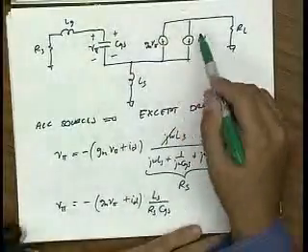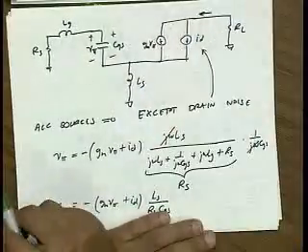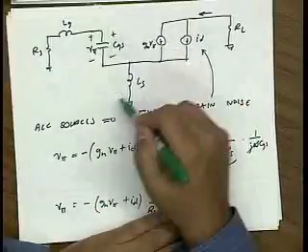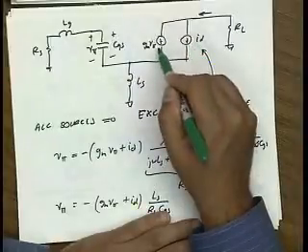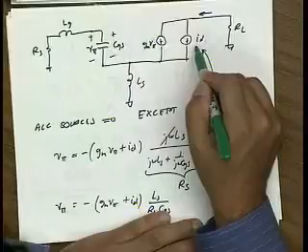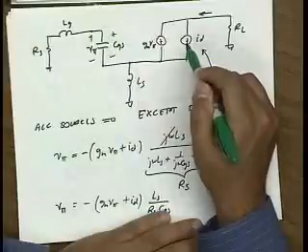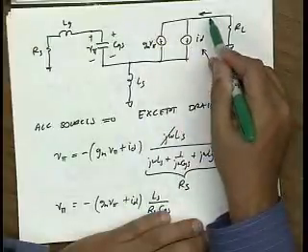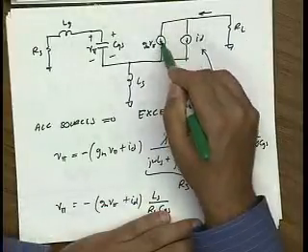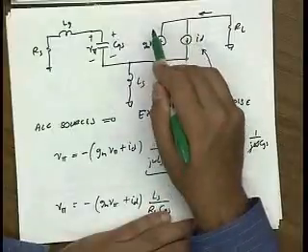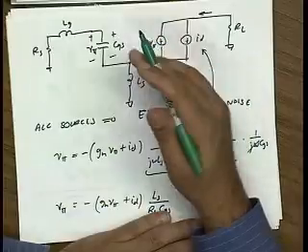The idea is that if I have one noise source here, and I'm interested in knowing the total noise drawn into my load, what I've shown in this calculation is that if I assume this is a deterministic current, then this current as a deterministic quantity is always half of this current pushing in the opposite direction. So it would cancel it out. Now if I'm interested in the statistics of this signal, I know that no matter what, at any instant of time, whatever this current is, it is completely correlated with this current, and it's in the opposite direction. Does that make sense?